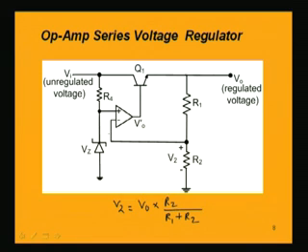So Vz minus V2, V2 is this voltage. So this voltage is the differential voltage which is available at the input terminal for this op amp. So the output voltage V0 dash is nothing but the gain of the op amp multiplied by the differential input Vd, which is nothing but Vz minus V2.